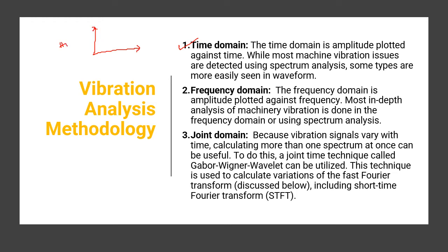This amplitude can be in terms of velocity, acceleration, or displacement. You get this type of curve, and by analyzing the amplitude and the time it takes, we can conclude about the type of fault.